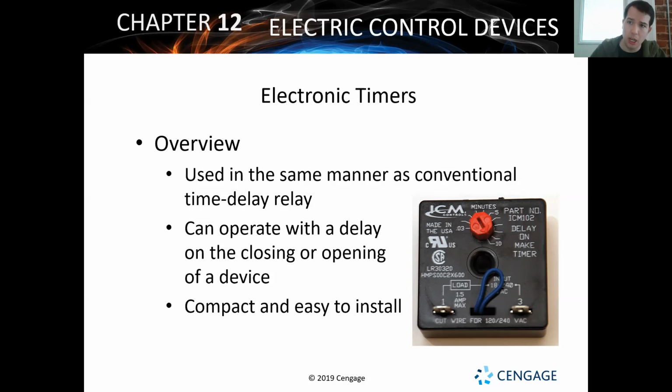What can happen a lot of times is when a system is switching between heating and cooling, for a heat pump especially, if it's been some crazy weather like we have in Virginia, where one day we're heating, the next day we're cooling, the next day we're heating, we need to allow the system enough time to restart. And even if it's operating normally, heating or cooling wise, that pressure change is going to happen. We're going to have lower on one side, higher on the other, all right? And we need to get it back to equilibrium before we start the compressor up again.